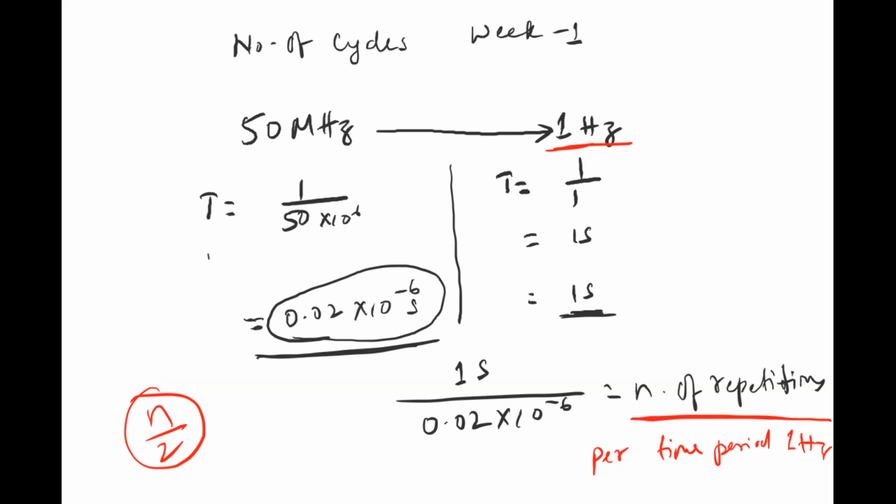And that time period consists of half the time being low and half the time being high. That's the reason we split the total number of cycles into n by 2 and n by 2: it is on for n by 2 and off for n by 2. So we'll wait for n by 2 cycles, and then the output gets flipped. Does that make sense to everyone? Do you understand it?